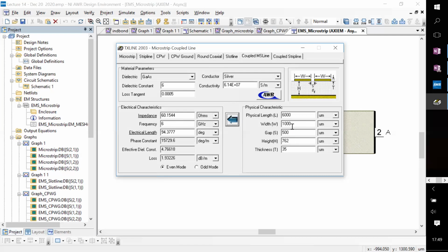The reason I'm saying this is that you would have expected that as they are brought closer, the capacitance would increase, and that typically causes the impedance to go down. But here it's going up. But this is basically because now the even and the odd modes are mixing. So that's why. But I also need to check one more thing about Microwave Office's convention for defining these impedances.